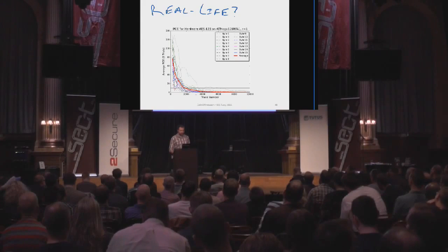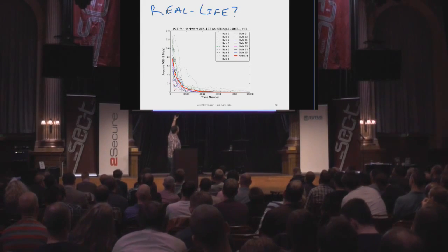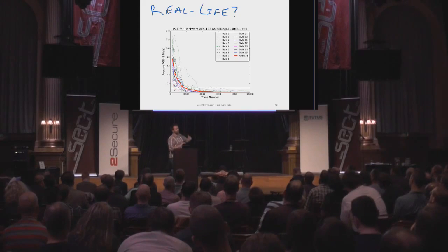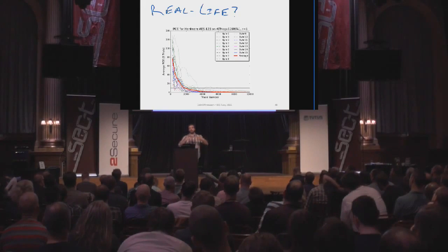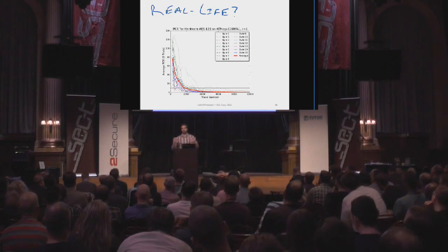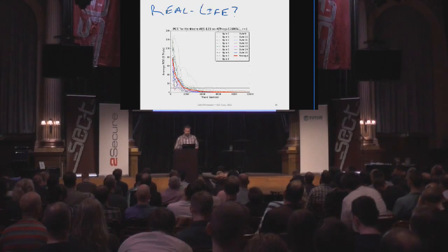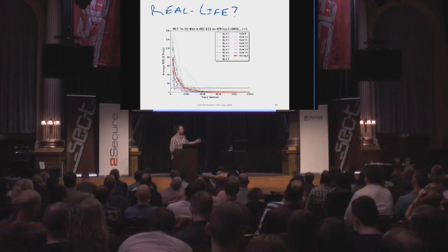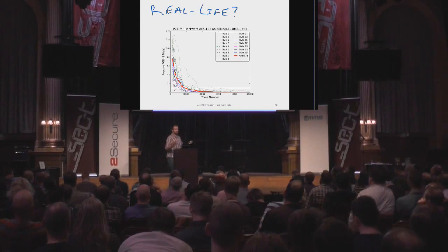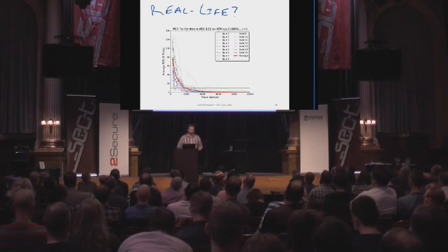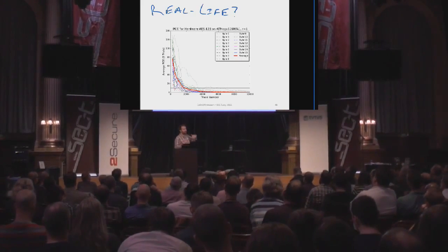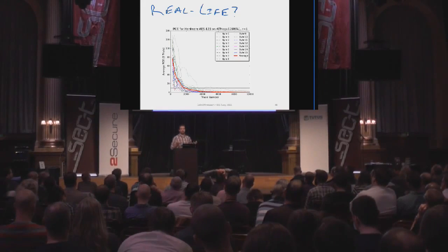And what this shows you is that, by the way, the scale on this one is the inverse. It's called the partial guessing entropy, so the entropy in the key. How many guesses do I have left in the key before I recover the correct one? If it goes to 0, no more guessing is needed. There's no entropy in my guessed key, so it's more or less recovered. What you end up with is somewhere around 6,000 to 10,000. It either recovers the key or it's so easy to guess it because there's like 100 guesses left, it's effectively recovered. And so what's interesting here is that, if I send it 10,000 messages, we're able to break this